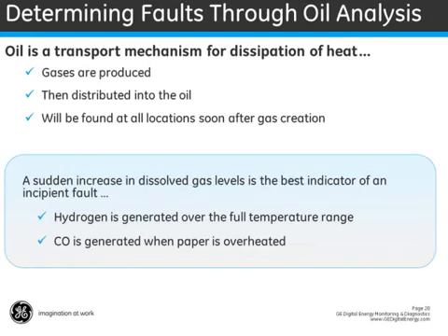in the standards. One of the simplest ones, often used to explain this phenomenon, is that acetylene, one of the diagnostic gases, is only produced when the oil experiences temperatures above 700 degrees centigrade. Sometimes you'll see this quoted as above 1,000 degrees centigrade, but suffice to say, very, very hot conditions within the oil, the sort of conditions that will only be found around an electrical arc.